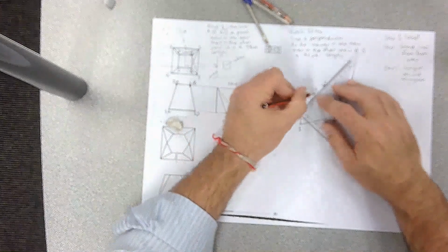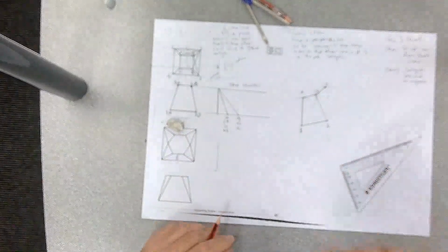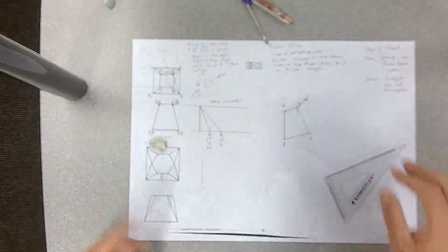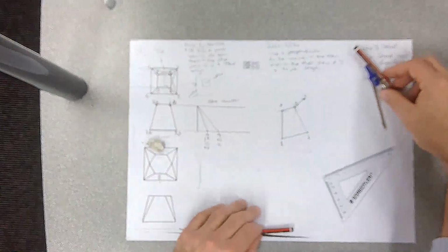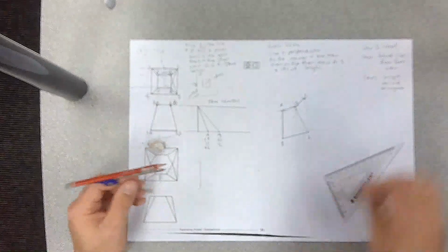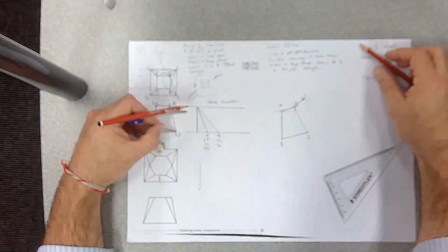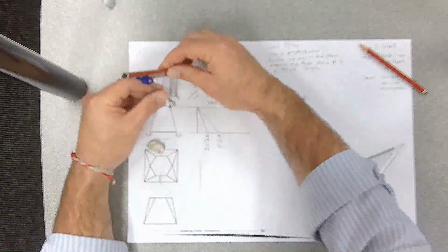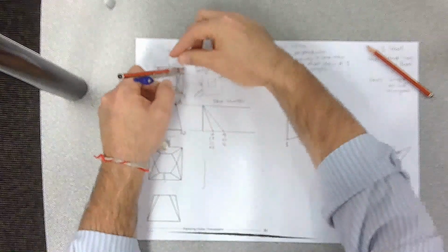Can you see how the angles can be quite extreme? Okay, we're going to run into our steps over here, and I'll rub them out if I have to. Okay, then we're going to go 2 to 3. 2, 3 is an end view in this diagram. So it's an end view in one view, in the other view it's a true length. So 2, 3 is going to be a true length. So we don't need to go over here for it.